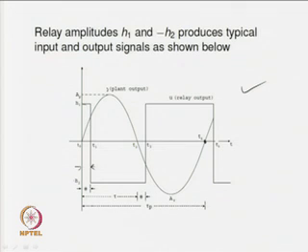So, let me introduce the half period of the output signal by the term tau. So, tau now represents the half period of the output signal. In our earlier analysis, we had used P u by 2 as the half period of the output signal, where one period was given by P u. Now, in place of P u, I use tau p for one period of the output signal.